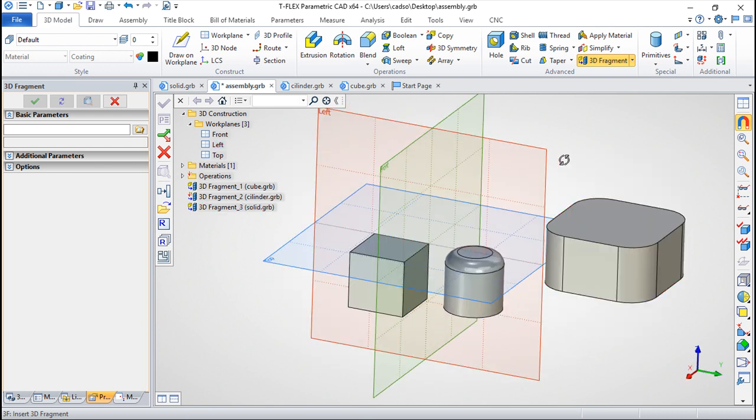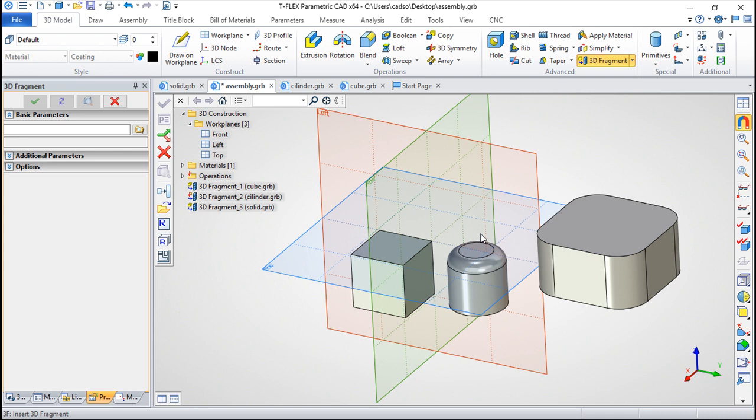So I can have also this very interesting feature, and there are more things to do in terms of these variables. We can connect these variables of the part with variables of the assembly file. There are very nice examples, and we will create a couple of them. But the very interesting feature of these variables is that you can have a part file with the geometry you want, with some variables to change the appearance, and you can insert that part file in multiple assemblies, and by the change of the value of the variables, you can have multiple part shapes starting always from the first initial geometry.